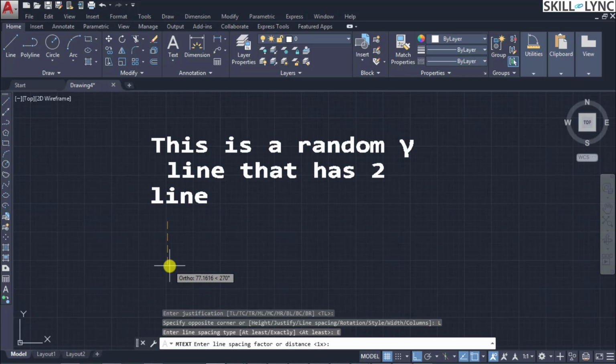When we selected the option as exactly, that is, it should be exactly so much distance, the default distance is selected, you can see in the angular brackets, that is 1x. Suppose the default spacing between the lines should be 2 line spacing. Now you can see that the line spacing value should be between 12.5, that is 0.25 times, and 200, that is 4x. So let us say the distance value as say 25.